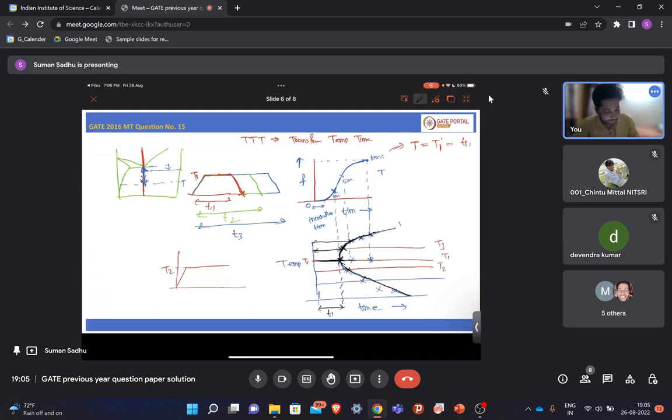So now this one C curve is for 10% transformation. Similarly, as I told, for 50% also you will get one curve like this, and again for 100% transformation we will get another curve. So this way basically C curves, or TTT, meaning transformation temperature and time, this curve is generated. Got it?